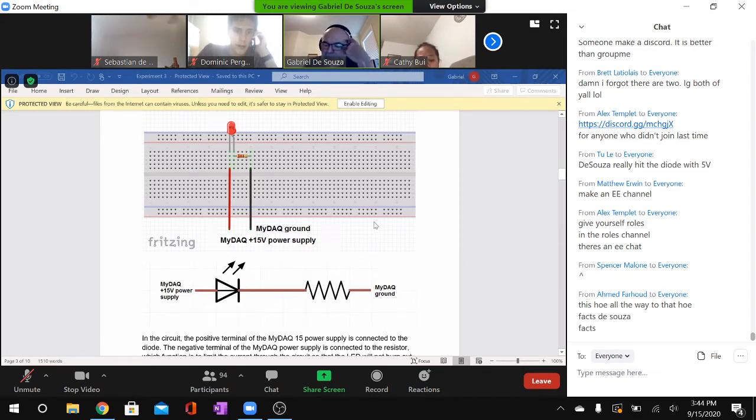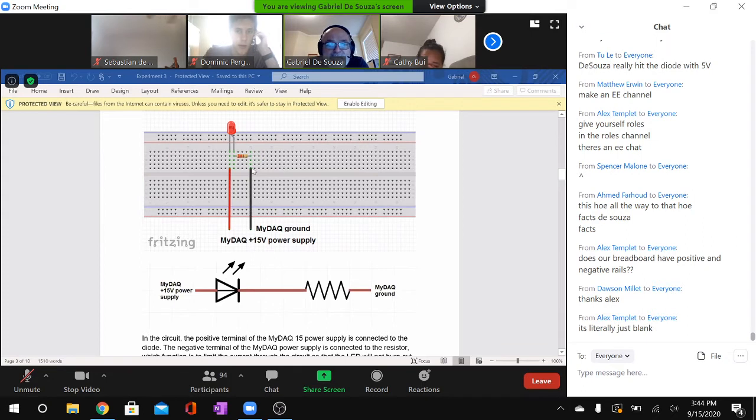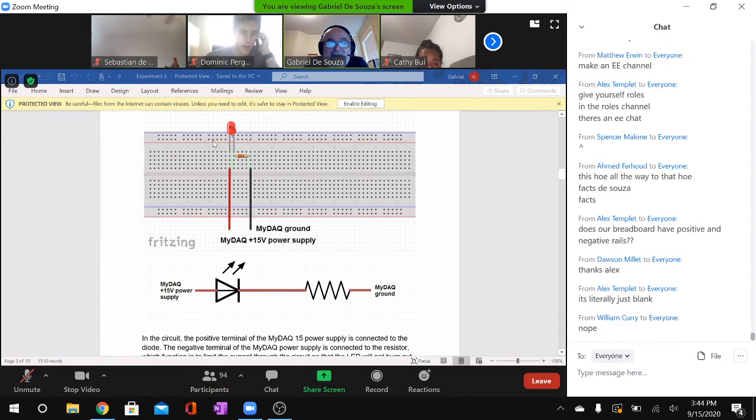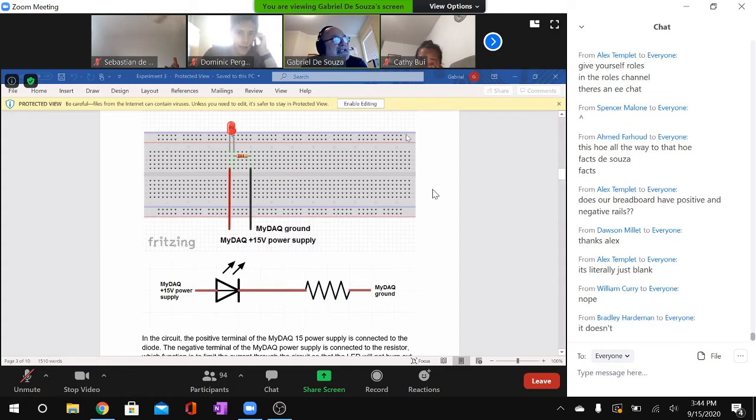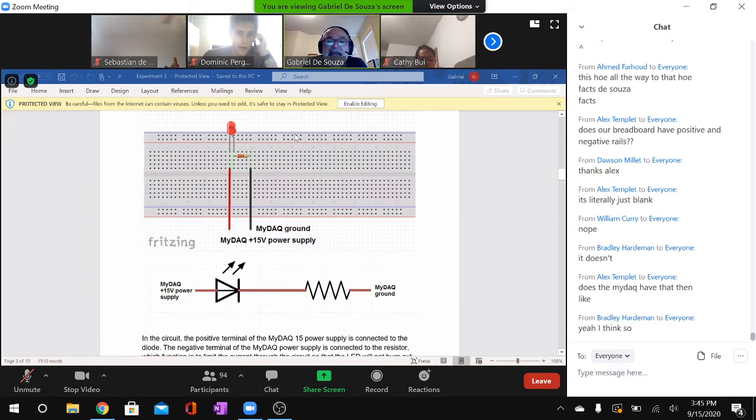What most people use this for is as a power bus. So I could make, for example, this row right here ground. So I would connect this from that to ground. I could make this row right here 5 volts DC. That would be my 5 volts DC bus. But remember, if you're going to use both sides, you need to connect them here in the middle, because right here there is a gap. This side is not connected to this side unless you make it so.